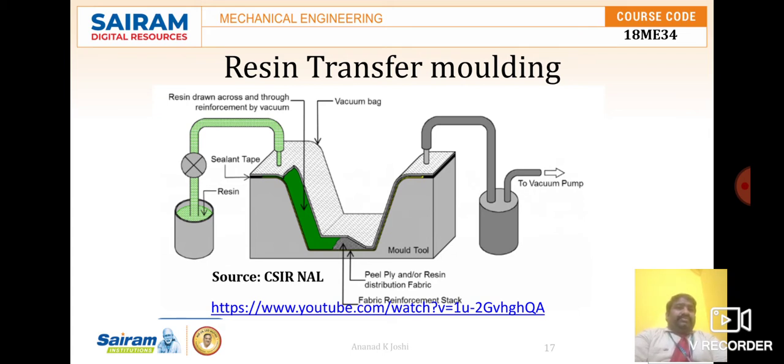Even for this material, generally we have a low pressure mold process designed to overcome the disadvantages of compression molding. In compression molding the charge is placed directly into the mold cavity, but in resin transfer molding the cavity is initially given a gel coat, and the mold is closed. A pre-calculated amount of thermoset plastic mixed with the desired additives is placed in the transfer pot.